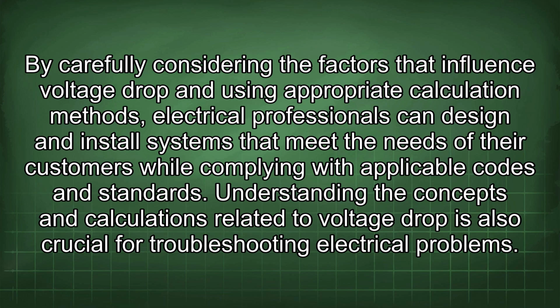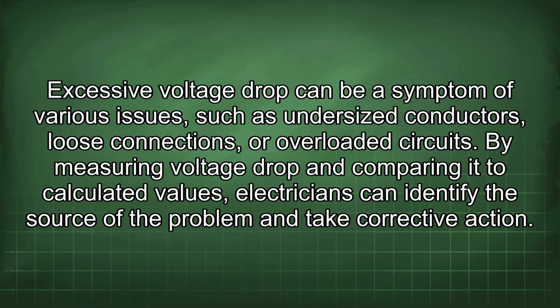Understanding the concepts and calculations related to voltage drop is also crucial for troubleshooting electrical problems. Excessive voltage drop can be a symptom of various issues such as undersized conductors, loose connections, or overloaded circuits. By measuring voltage drop and comparing it to calculated values, electricians can identify the source of the problem and take